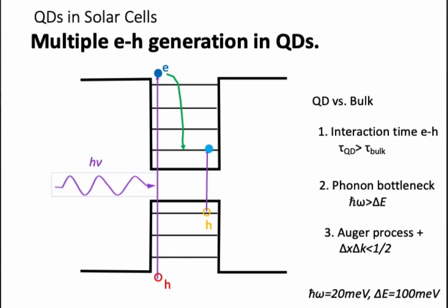Semiconductor quantum dots may by themselves be a favored place for having one photon in and two or more coming out, as we talked about. This is called quantum cutting. It is by creation of multiple electron-hole pairs, sometimes called multiple exciton generation, unfortunately. You may ask, why not collect the electron-hole pairs directly, instead of creating photons that have to be collected by the solar cell? Good question. It's just not so easy to do that efficiently from the quantum dot.